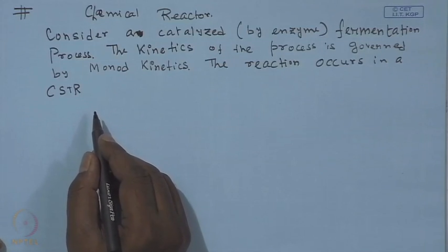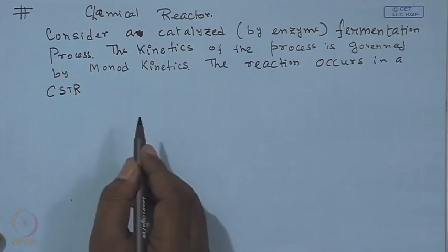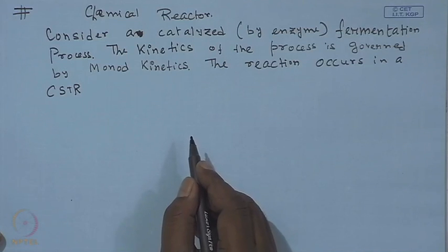It is a continuous stirred tank reactor where the reactor is being stirred all the time and the feed comes into the system and goes out of the system. Since the reaction volume is appropriately stirred, it is assumed that the concentration and temperature in the reactor volume are uniform throughout, and it is expected that whenever you draw a product out of it, it will have the same concentration and temperature that exists inside the reactor. That is the principle of a continuous stirred tank reactor.